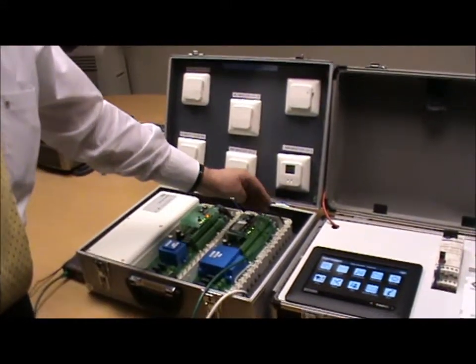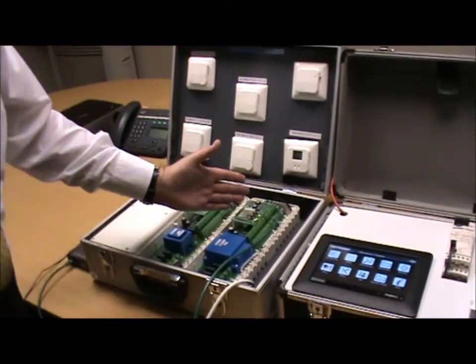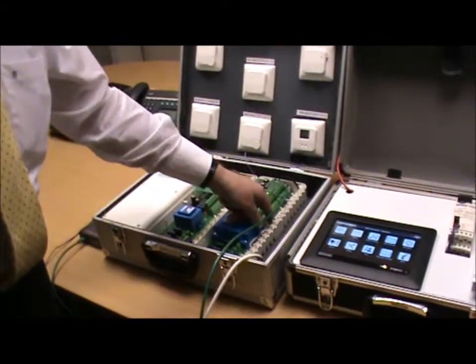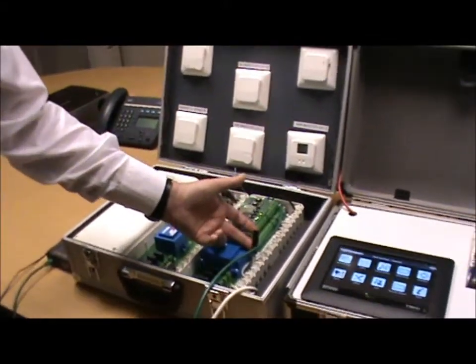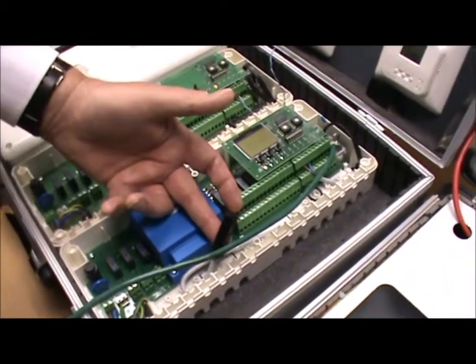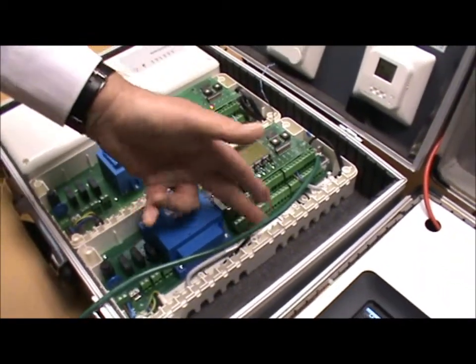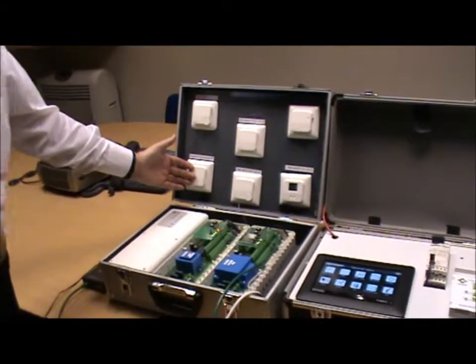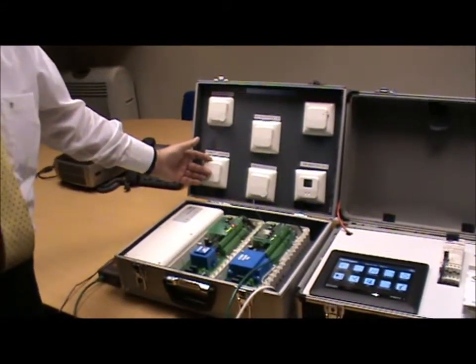We also have a number of outputs on the master which can be used to drive a 3-port or 4-port modulating valve. We also have a sensor which measures supply water temperature, and if we were to move in towards the cooling aspect, then we also have humidity sensor to actually monitor dew point control.